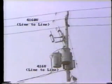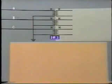Let's consider the case of a distribution transformer, say 4,160 volt primary to 416 volt secondary connected Y-Y. This could be a three-phase unit or three separate single-phase transformers as shown here. On a single line diagram, this arrangement would probably be shown like this, with the Y-Y symbols indicating the connections. More detail will be shown on the circuit diagram.